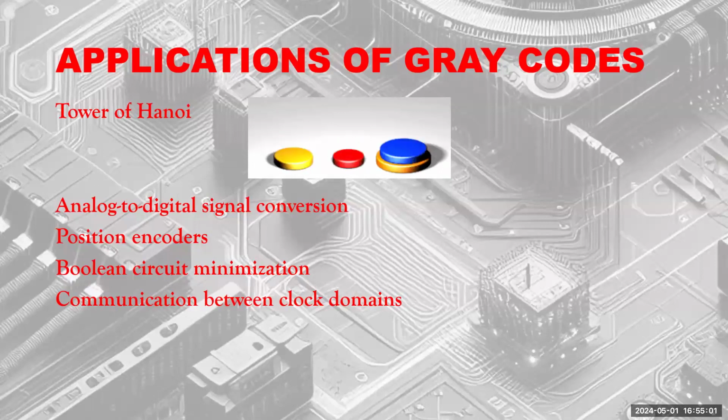Anyway, once you assign with that method, the advantage is any state transition has only one state bit changing, and this has a massive energy saving implication on the next state determination, because all your next state cloud, which is a huge amount of logic gates, is seeing only one signal change, one bit of the state.